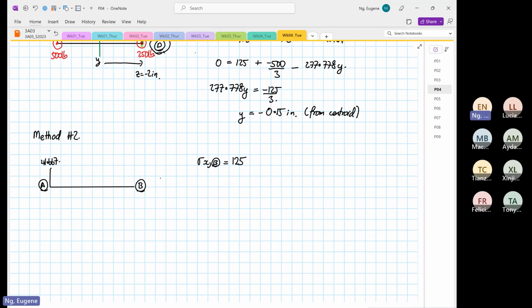And then we have to write down the My. So My is 800 multiplied by 2 divided by Iyy, which is 9.6. I've not put in the plus or minus yet because I don't know whether it is positive or negative yet. So this will be 540 multiplied by 0.9 and then divided by 1.944.